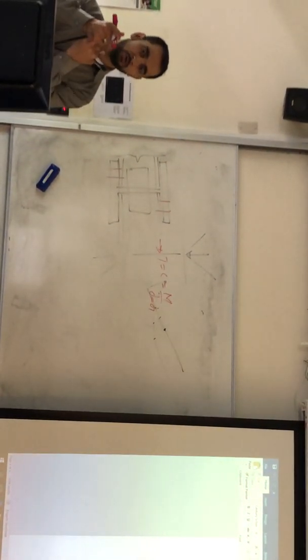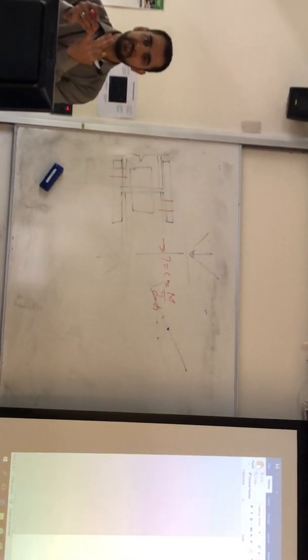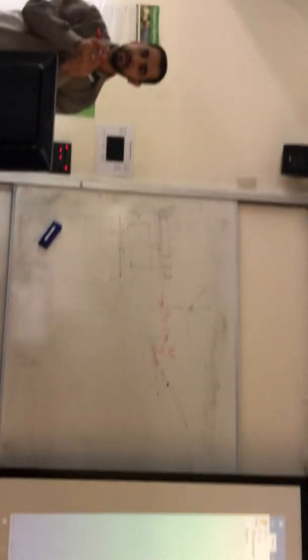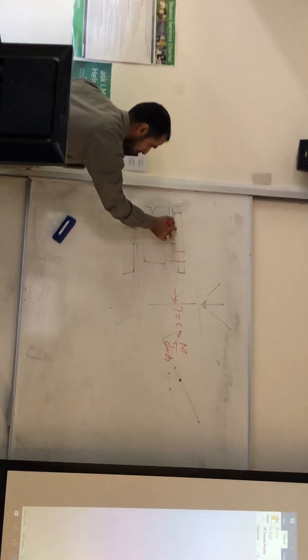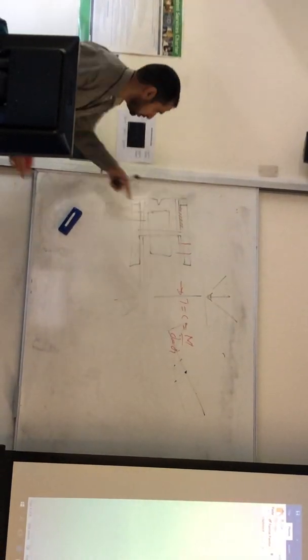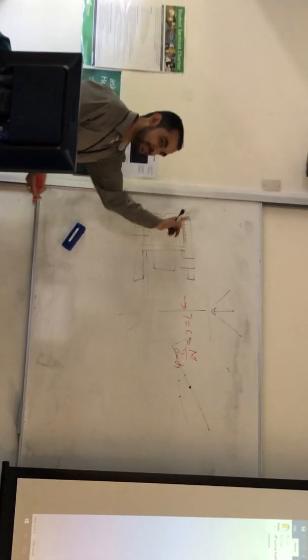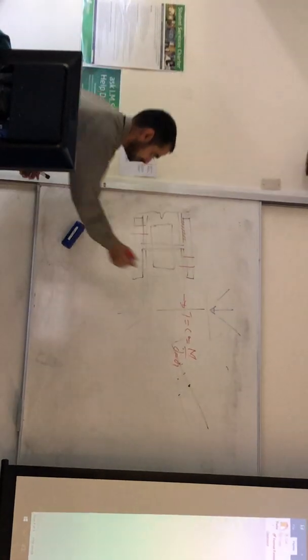Two types. No shear. Tear out, which is the tensile capacity of the net cross-sectional area, and bearing. Those are the two. Then from the plate, where does the load go? Back to the connection on the other side, whether it's bolt or weld, and then back to the flange. So in our case, it's the weld. What is the weld length available all around? Let's say 200 millimeter. What is this tension?